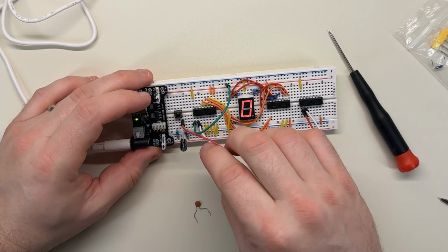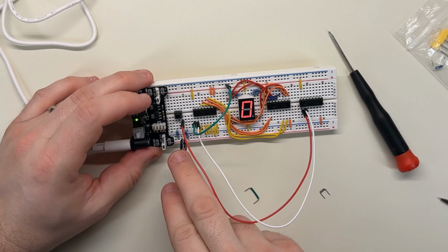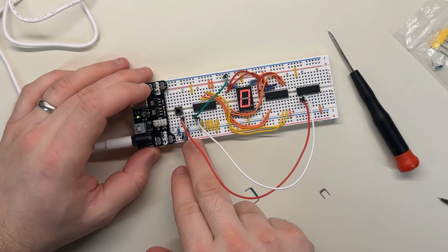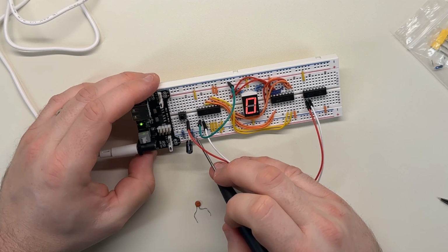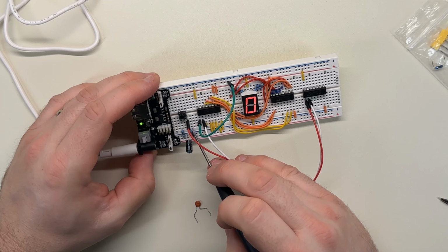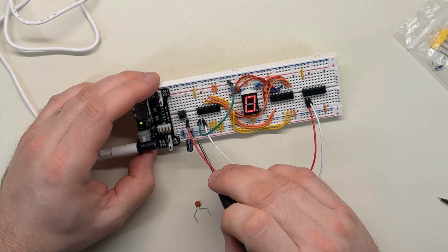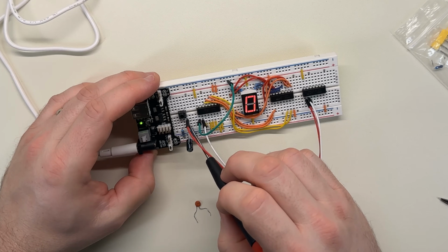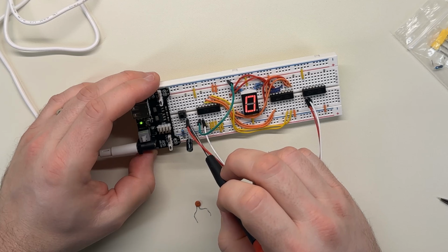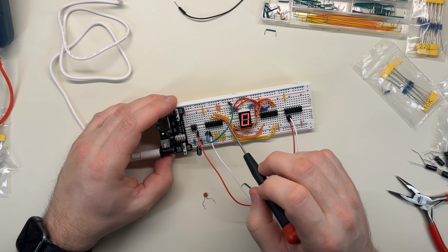So I think that means that I hook it up almost identically to how I have this here, because right now when I turn on the circuit, and the button's not pressed, current should be going through this resistor into the capacitor and charging it. That means that initially this side of the resistor is positive and this side is negative essentially, and increasing as the capacitor fills, which is pretty much exactly what we want.